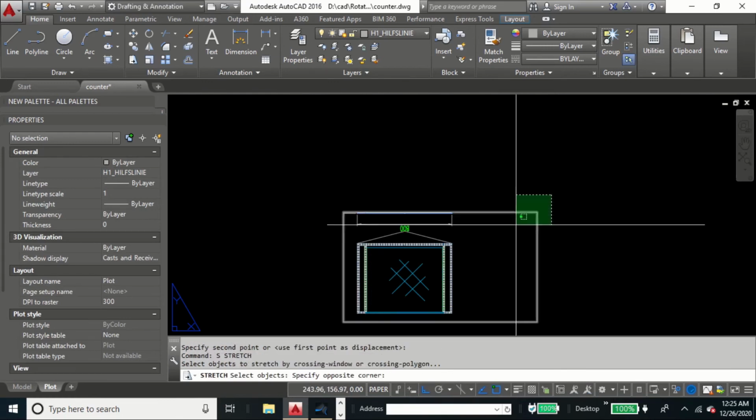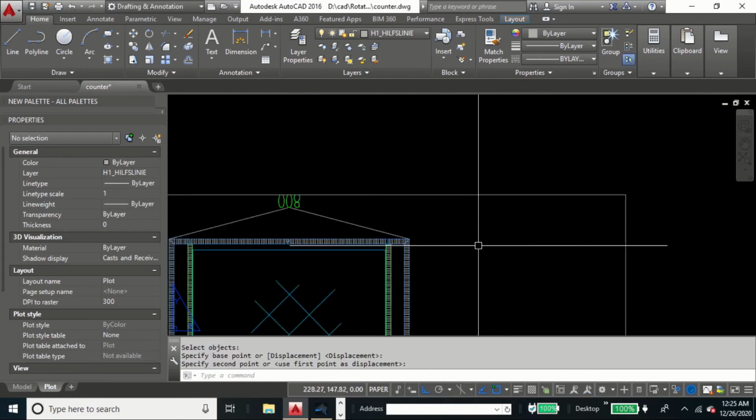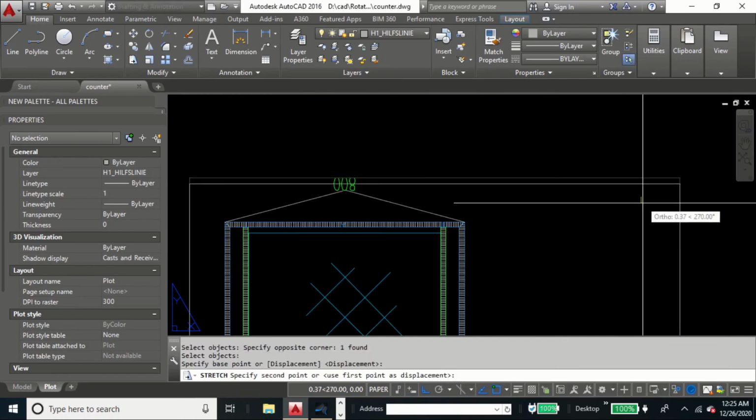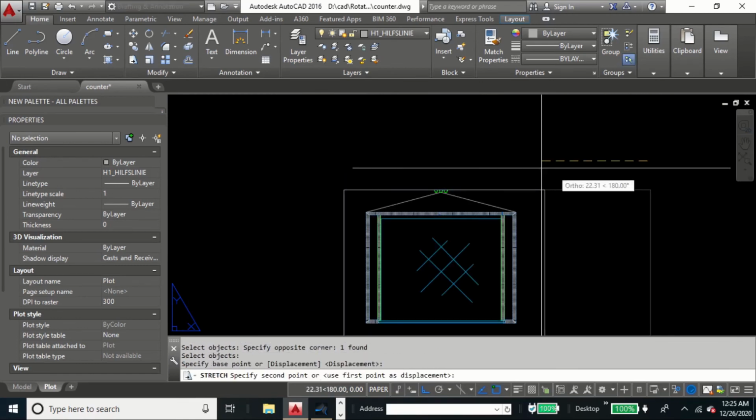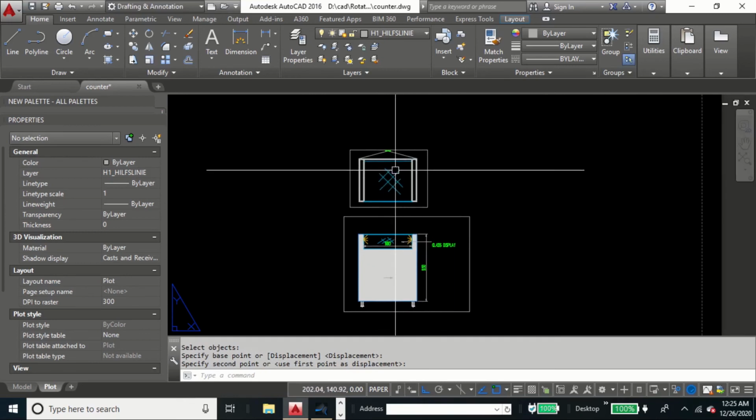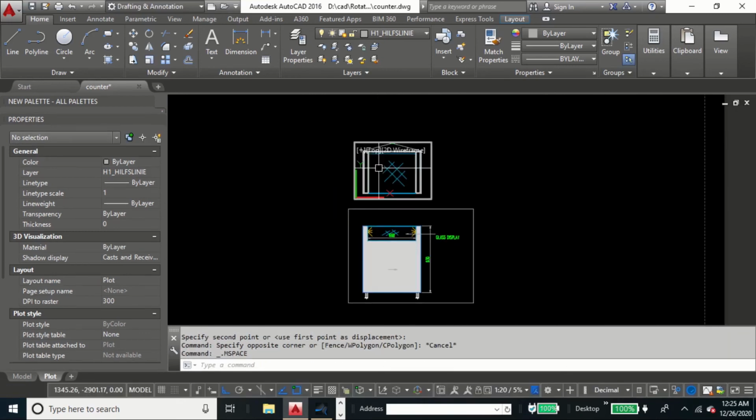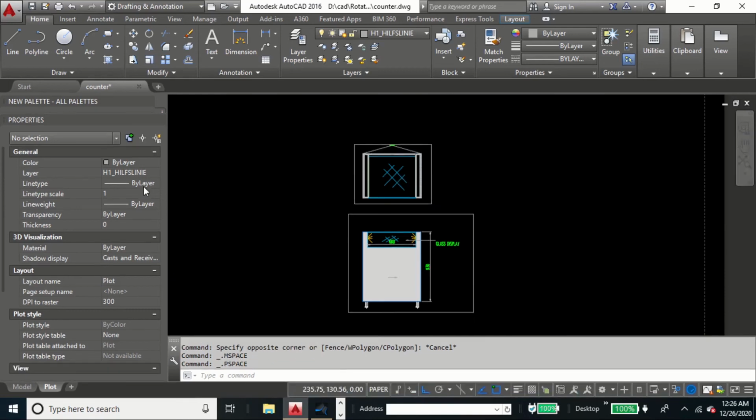We haven't put any dimension for this object. That's fine. We don't want that, just for the view here. Now, what I want to show you is, if you now double click, there is no problem of that zooming out issue. That's because we have to make the UCS follow back to 0 once we have done with our work in the model space.